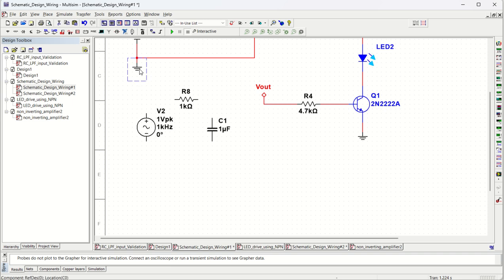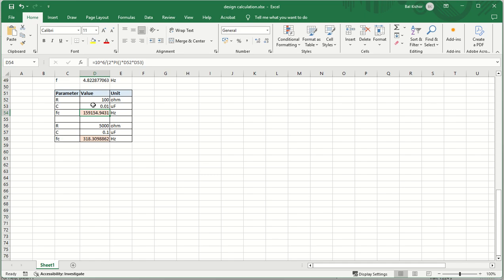So after this RC circuit, it will go to page 2. That's all. So this is my signal. Let us say this is getting generated by some means, and we are going to use that. Just make sure that this RC cutoff frequency is much higher than the required 1 kilohertz signal. So if you want, you can change that. So let us say we have this one.